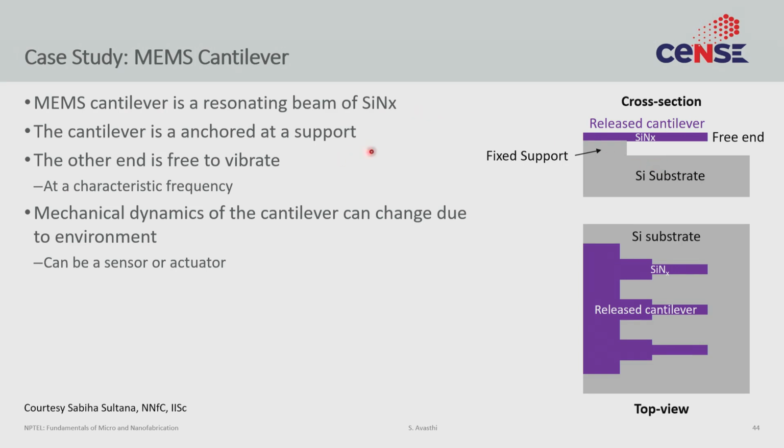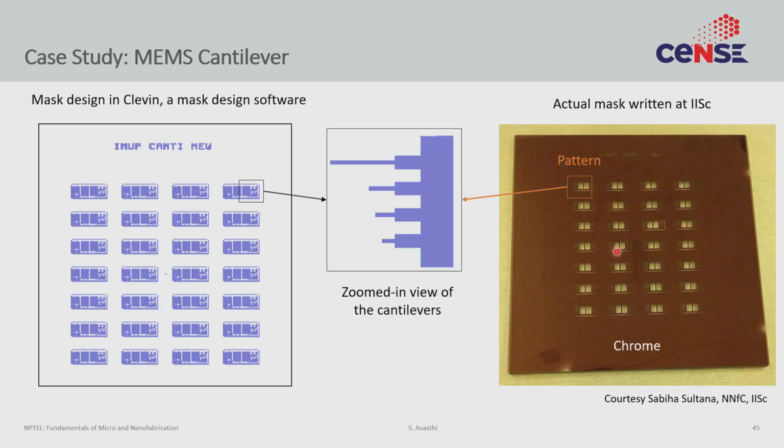Just one aside: typically MEMS devices, especially cantilevers, are designed to vibrate at a certain frequency, and the vibration frequency is very strongly dependent upon the geometry of the cantilever. So in order to have a very precise device that vibrates at exactly a certain frequency, you have to have very precise control of the geometry. That's something to keep in mind.